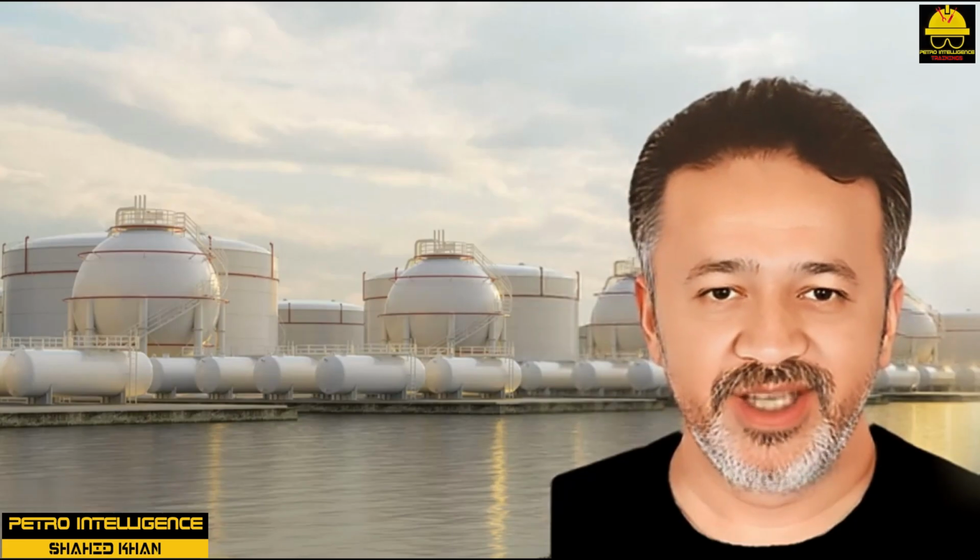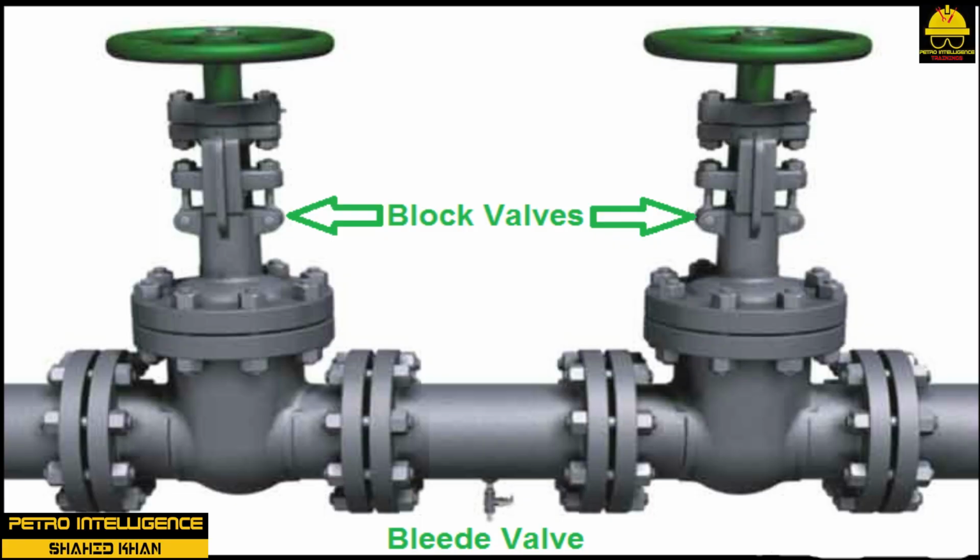Double block and bleed. A double block and bleed system is frequently used to stop flow. This is not considered a complete shutoff, however. The double block and bleed consists of two valves in line with a smaller valve opening to the atmosphere between the two line valves.